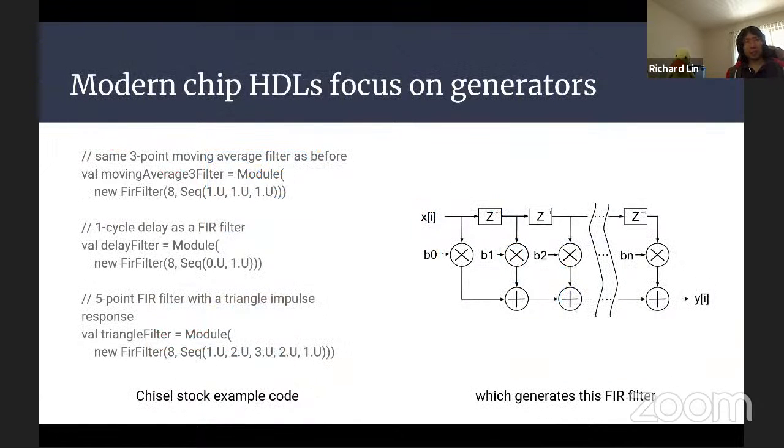In the adjacent digital logic domain for chip design, hardware description languages like Verilog have been common for decades. However, because of limited parameterizability, designers often have turned to ad hoc metaprogramming approaches, like the dumpster fire that is writing Perl to write Verilog. Recent languages, like Chisel shown here, have focused on structured hardware generation, such as embedded domain-specific languages using their host language for this kind of hardware metaprogramming.